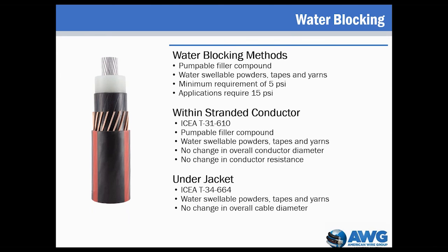When the water blocking method is employed within the stranded conductor, care must be taken so as not to interfere with or contaminate the semiconducting conductor shield layer. This has been an issue with some pumpable strand fillers. Water swellable tapes and yarns are becoming more and more common as a preferred water blocking system within the stranded conductor. With no change in the overall conductor diameter and conductor resistance, standard terminations such as compression lugs are not a problem.